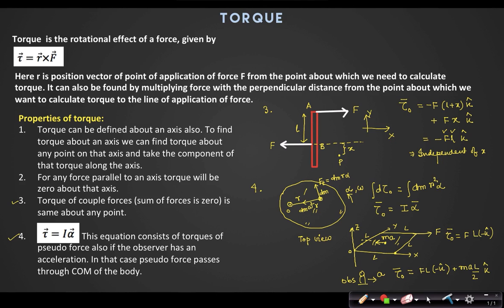Always find the torque of the real forces, with respect to the ground. Torque about some point you always find with respect to ground, with real forces only.